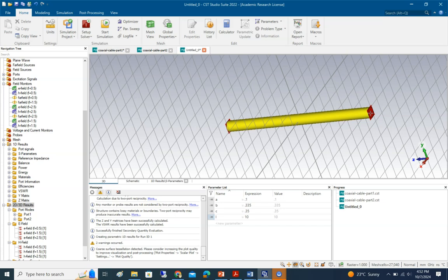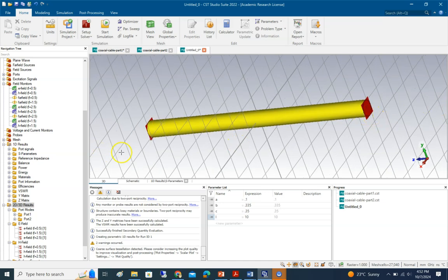In the other file which you will be opening, I recommend using a separate file and using one end as a waveguide port, with the other end terminated with a discrete port. Okay. All right. Well, I'm not going to do that. Rather, I will just remove one port.